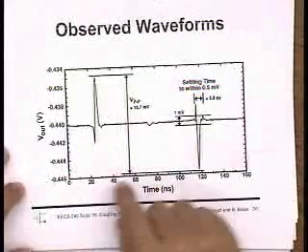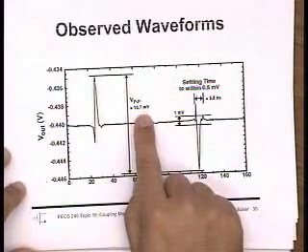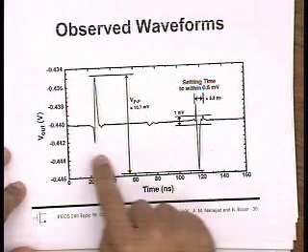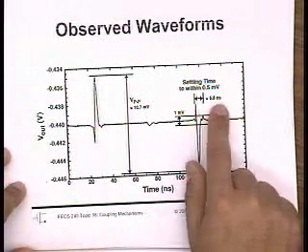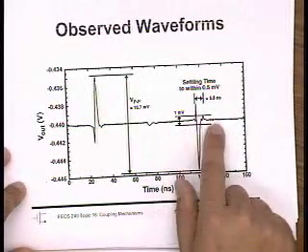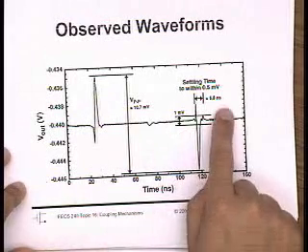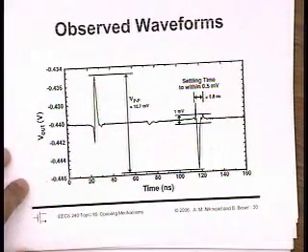The magnitude of the voltage is quite large, on the order of tens of millivolts. And the settling time for this transient to die out is quite significant: about 7 nanoseconds to get down to just 1 millivolt. If you want it to get down even lower, you're looking at maybe 10 nanoseconds. So if you're building a system sensitive to noise on the order of a millivolt, this is going to be an issue.